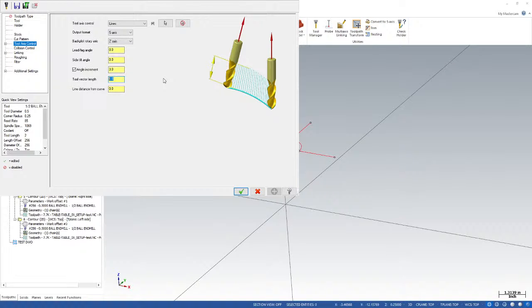Now, why would we want to change that 3D vector length? Well, there are a couple of reasons. The post processor is going to take, we can think of a vector as a line. So for this discussion, in your mind, just think, all right, we've got a bunch of lines in 3D space. And the way the post processor works for 5-axis output is that we take that line and we use it with vector mathematics and matrix mathematics to resolve two angles in 3D space.